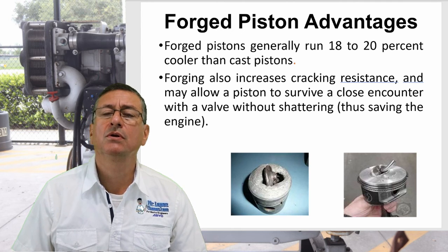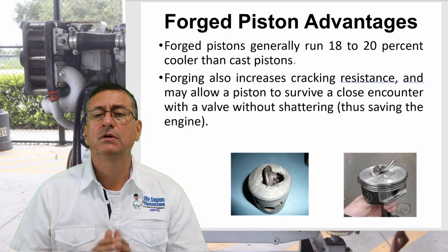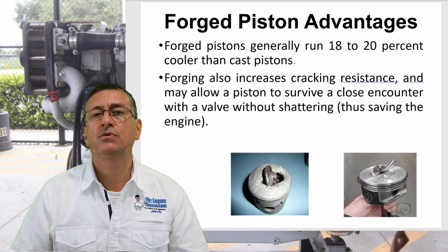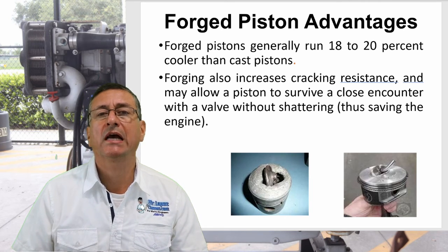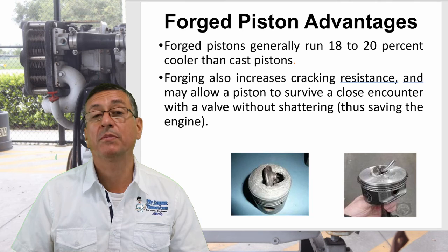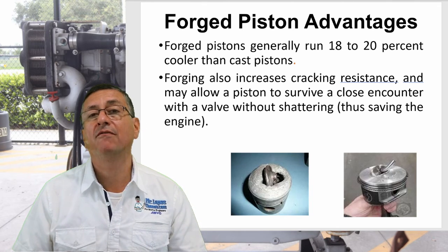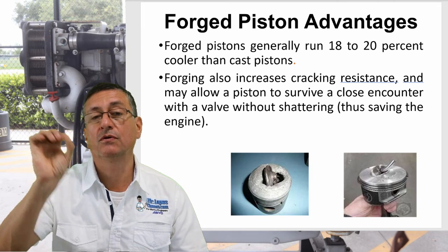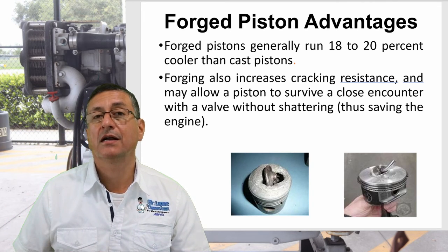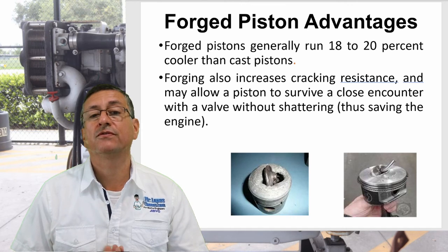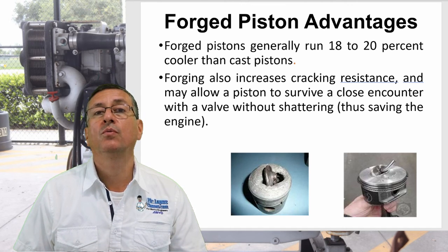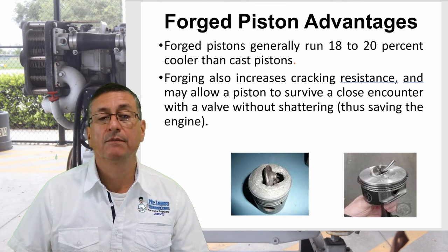They run with a lower temperature. They run with lower temperature in comparison with the cast material. It's around 20% less temperature. Excellent, excellent. And they avoid the propagation of cracks. Yeah, they are crack resistant because the surface is hard in comparison with the cast material.